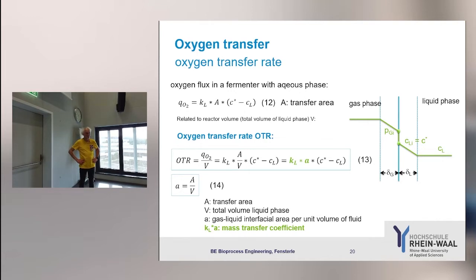Also have a mixture which is going to break down bubbles too. Yeah. So first of all, your mixing process will result in that you break down the bubbles. Yeah. One thing. And the other problem is that bubbles try to fuse. This is called coalescence. And this is what you don't like to have.